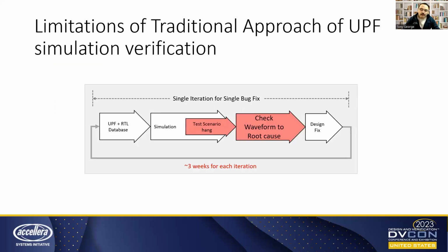The traditional approach to verify X-propagation is to simulate the functional verification test case until any data integrity checks fail or the X value shows up in the output of the DUT. But by then, the X value has already propagated widely inside the DUT. So this approach adds delay in detecting bugs in power-aware simulation. Here, we also have to notice that we need to wait until we have a mature design to start the verification because we need the design to support data integrity. But reaching such a design maturity also takes significant design time.